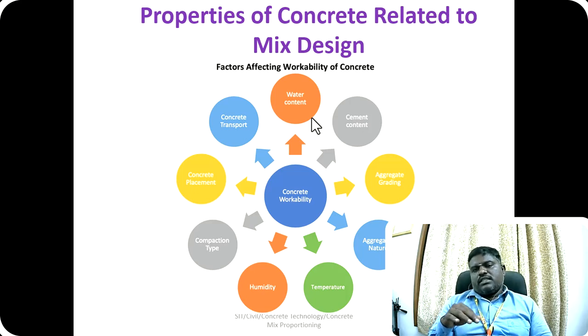So in that, the workability is going to be affected by a lot of factors such as water content, cement content, grading, aggregate nature, concrete temperature, humidity, compaction type, concrete placement, and concrete transportation. So these are the predominant factors which affect the workability of the concrete.